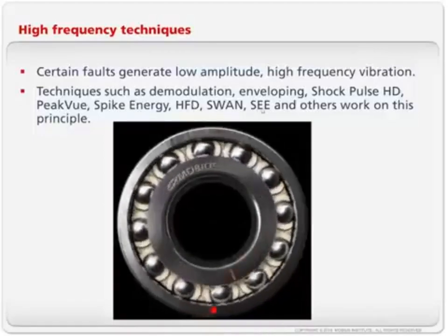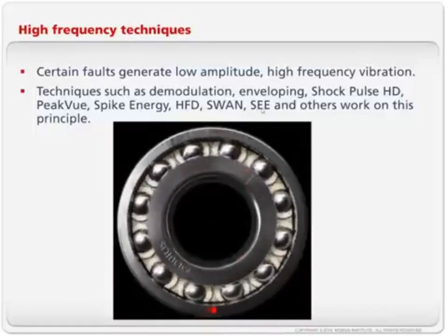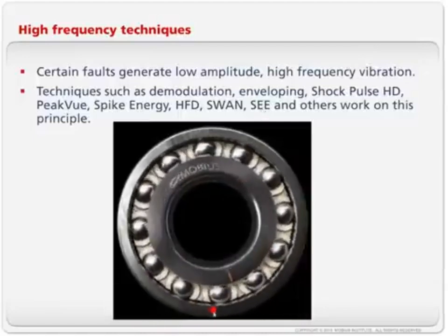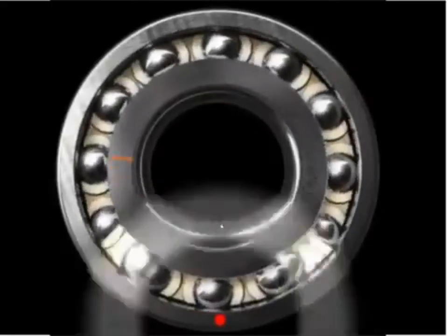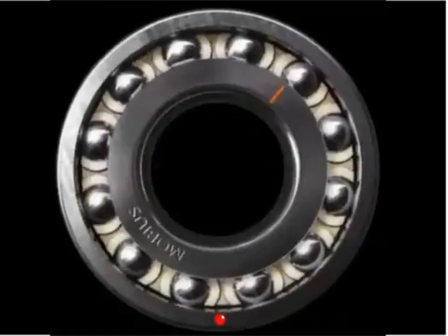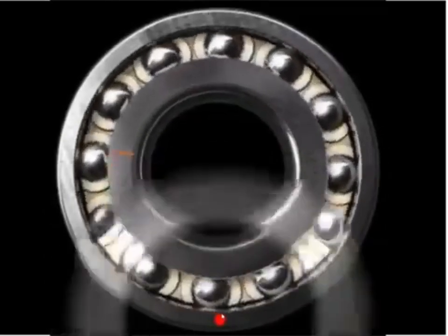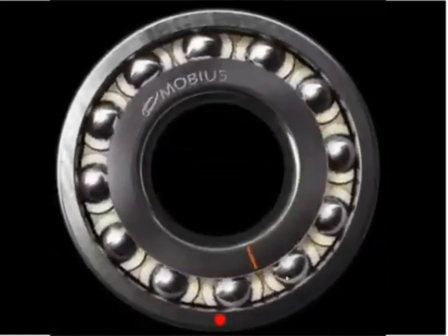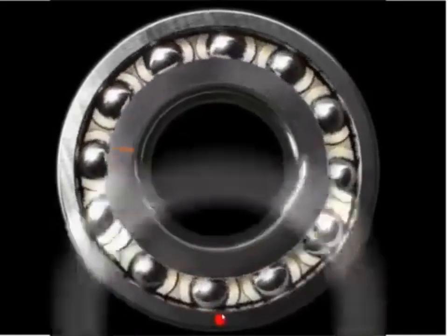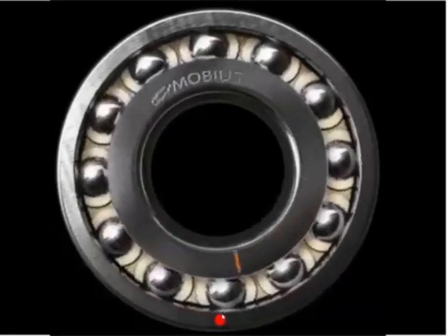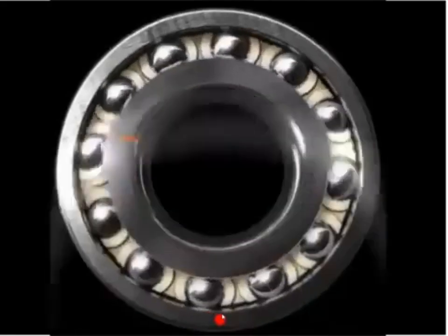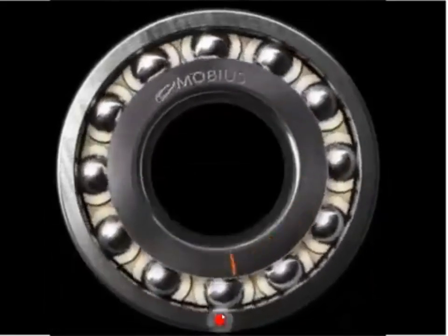C. There's a lot of different technologies that utilize the fact that if, for example, we had some damage in the outer race, in fact, I'll go to a bigger picture of it. If we had some damage, like a little spall or a little crack or even a subsurface defect, each time one of the rolling elements rolls over the top, we get this ping of vibration. It's very quick. It rushes through the metal of the machine. It's very low amplitude, so it's hard to detect.